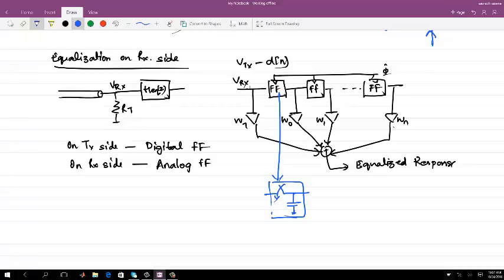And you are right that if you are using a capacitor, the voltage will basically drop, means for this capacitor and for this capacitor, right? Let's say it's very small, maybe even 2 or 3 femtofarad. But you charge this voltage, then you again charge through a switch, and this switch is not an ideal switch, it's a resistive switch. So you will have losses, you will drop.